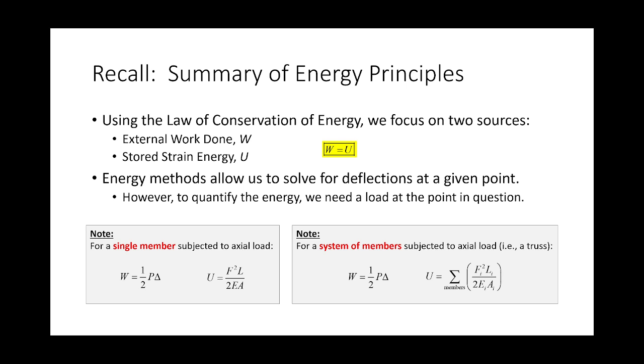And as I mentioned in the initial part of the video, deflections are incredibly, incredibly important in structural engineering. Number one, we have many designs where we simply have to design the system such that it doesn't exceed a certain deflection. In your project, you'll have that limitation as well. Like, for example, a common deflection limit for beams in buildings is L over 360.